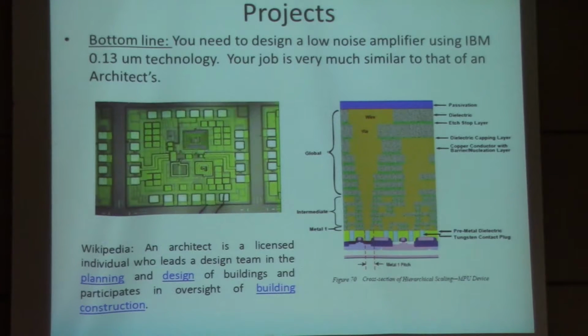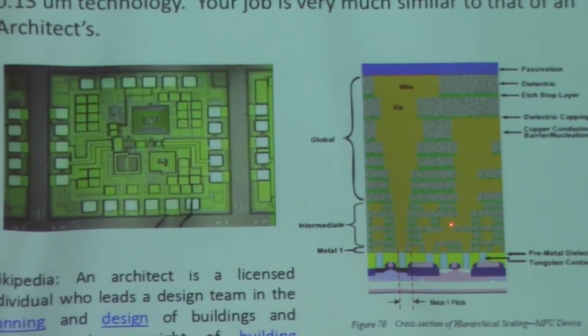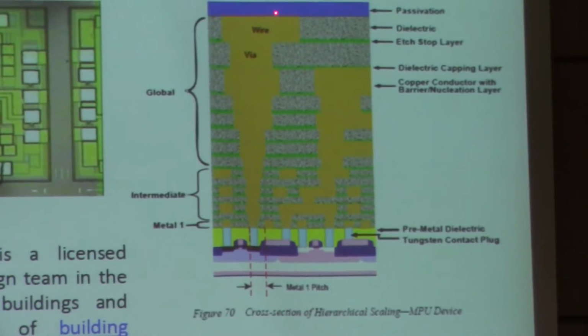Okay, for the all-CMOS one, so-called CMOS RFIC, like the low noise amplifier, you need to use transistors, inductors and capacitors. These are the capacitors. If you cut the wafer, the chip, and look at the cross section, your transistors are on the silicon, at the bottom. And this area is called the interconnect area.